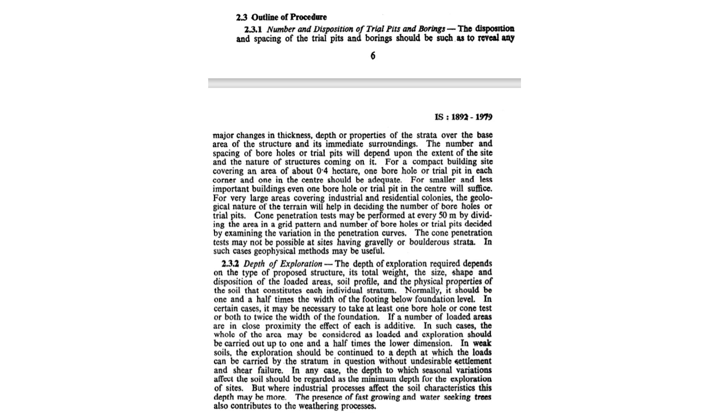So once you take a trial pit, you will get an idea about the soil profile which exists underneath. And once you get an idea about the soil, you can recommend a proper boring technique which is suitable for the soil. Okay, so that is how it is done. So as I said, these pits and all can be taken even during site reconnaissance if you can take some workers along with you.